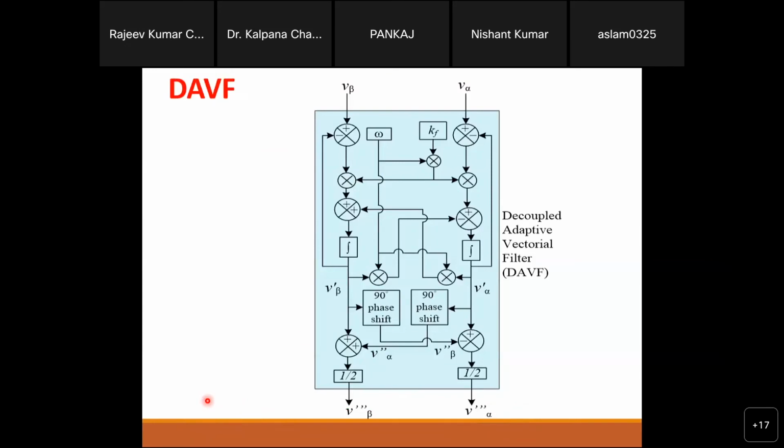For example, here, this is the block diagram of that. Three phase comes through the Clark transformation with alpha beta, or you can go with this one, means just take the grid voltage here and 90-degree phase shift here, and go through these calculations, and then finally you will see this is your grid voltage, no need of any Clark transformation or all, and like that.